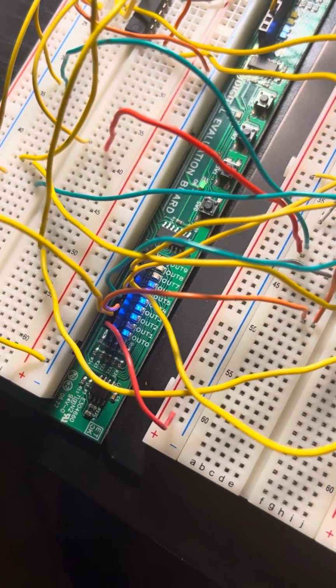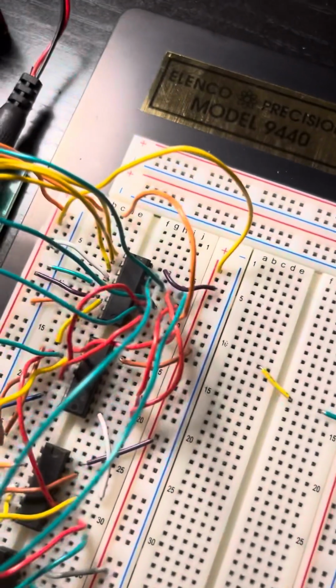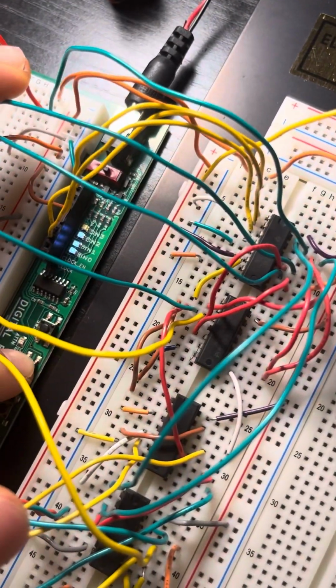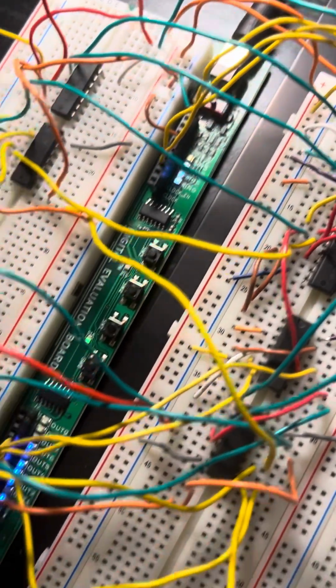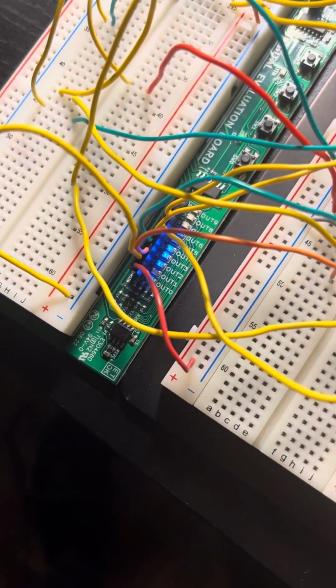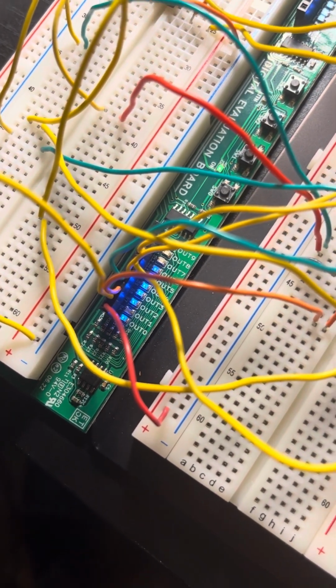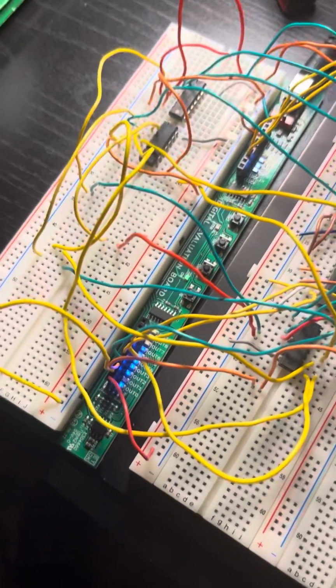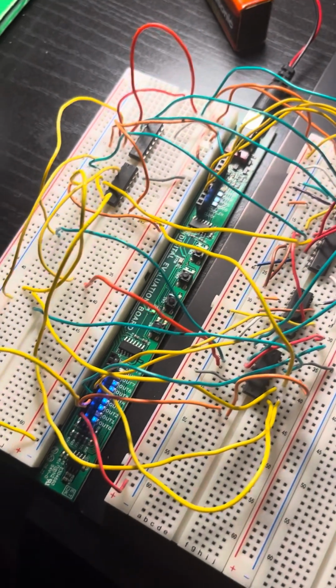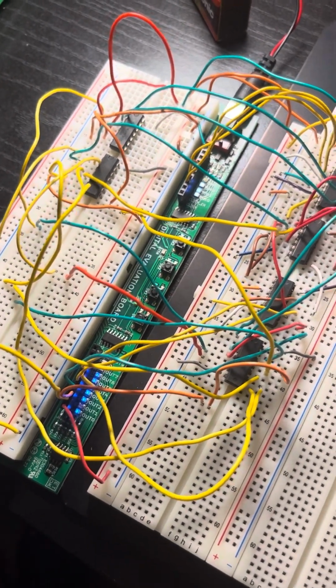So if we first test 110 as our input address, we see 1011111 is our ASCII output. And lastly, if we also turn on input 2 such that we have 111 as our address, we see the same ASCII output, 1011111. So that's my read-only memory circuit for the 6-letter word endure with underscores.